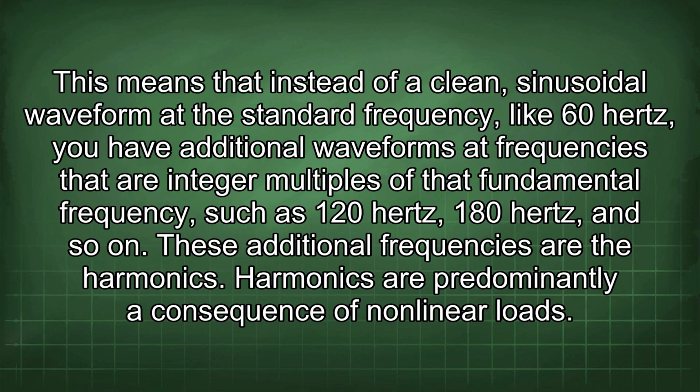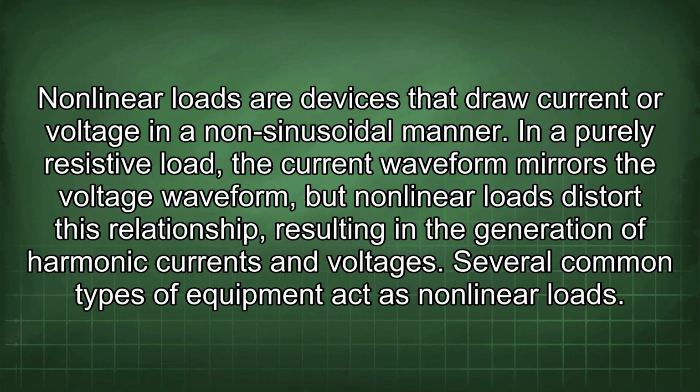Harmonics are predominantly a consequence of nonlinear loads. Nonlinear loads are devices that draw current or voltage in a non-sinusoidal manner. In a purely resistive load, the current waveform mirrors the voltage waveform, but nonlinear loads distort this relationship, resulting in the generation of harmonic currents and voltages. Several common types of equipment act as nonlinear loads.